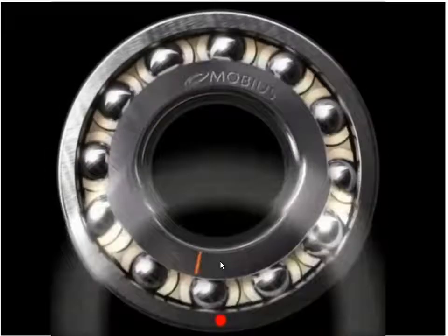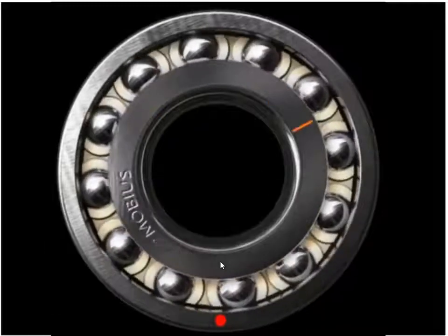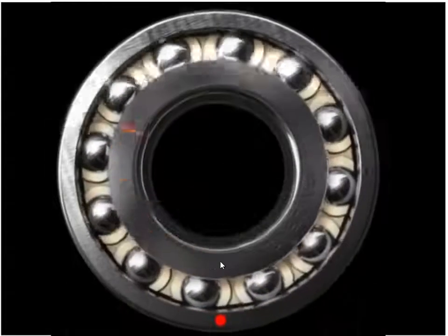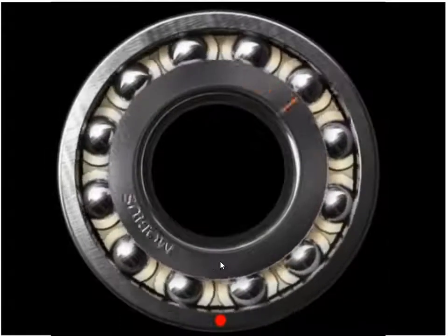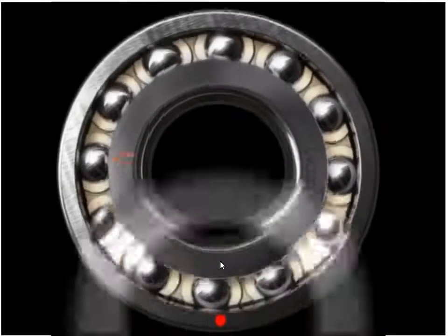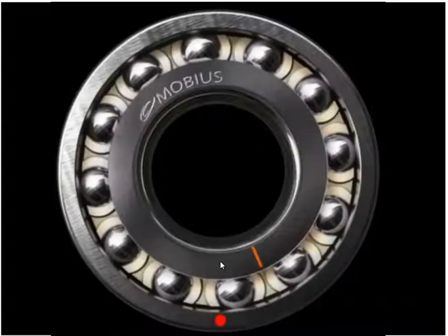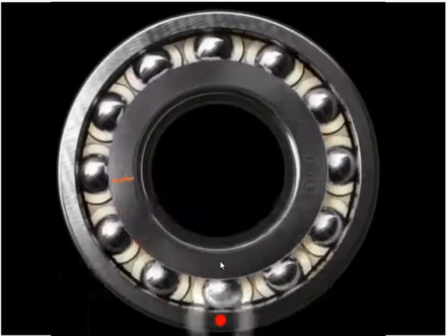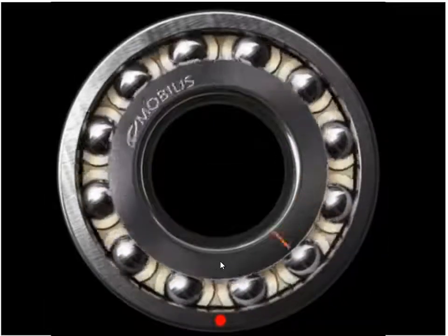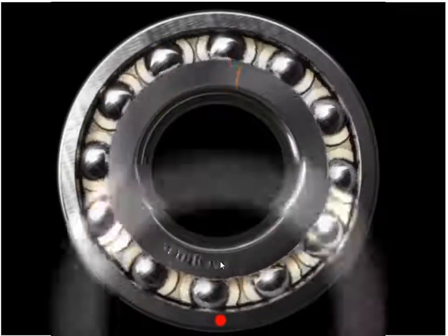Now there's a lot more I could say on this topic, but basically we can detect that because at the very earliest signs of a problem, either inside the bearing or with gears and other metal-to-metal fault conditions like looseness and broken rotor bars, in that earliest stage we may not see any normal vibration.